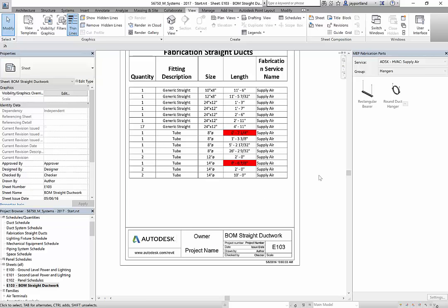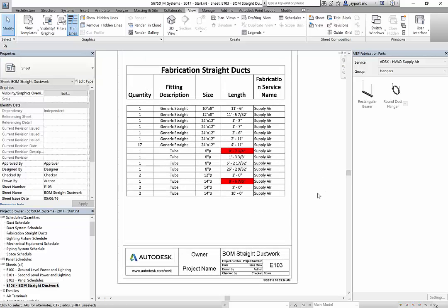What you're seeing here is the capability to leverage not just the building information model, but you're able to think outside the BIM and get some information that's relevant to the design work that you're creating, right? So that's one way that we can leverage the schedules using conditional formats. And I like the way that this particular schedule looks. I do have to warn you guys though, the schedules are limited to whatever the parameters that are available to you. That's just the nature of how schedules work in Revit.